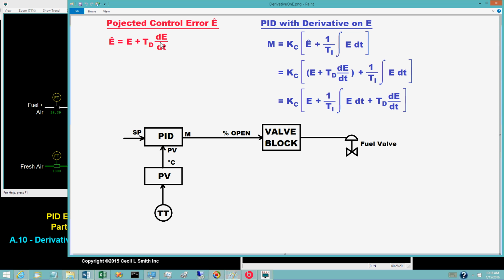The value of dE/dt reflects the rate of change of the set point as well as the rate of change of the PV. Issues arise for changes in the set point. Except for abnormal events such as equipment malfunctions, abrupt changes in the PV do not occur in process applications. But abrupt changes in the set point occur routinely.